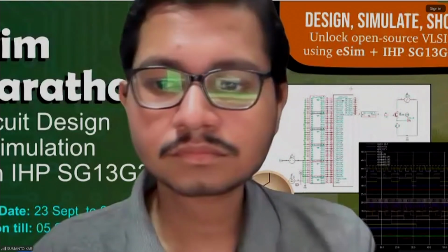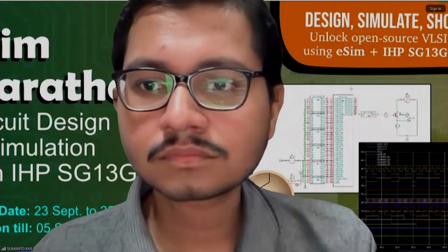ngSpice has access to qualified Spice libraries for the IHP 130 nano BiCMOS process. So all has been silicon verified. Complete schematic entry and transistor simulation. You are moving to KLayout.